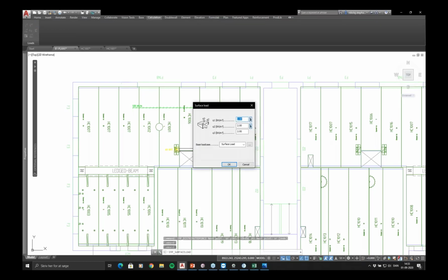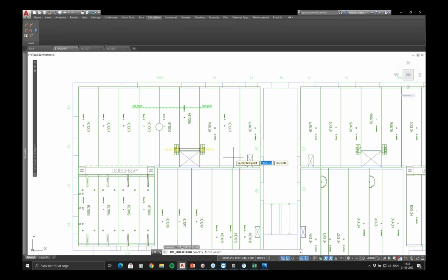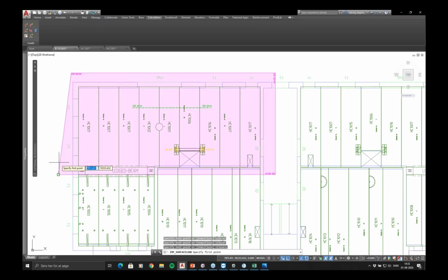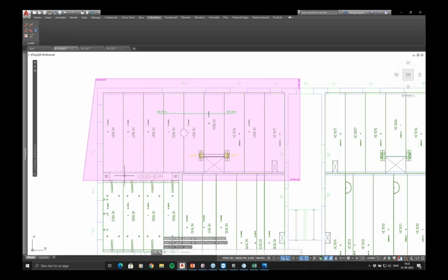And of course I have some surface load as well. And the surface load, if it's the whole surface, I can actually just do like this. I don't even have to think of it hitting the right place. It depends on what I'm calculating, of course, but here I can do whatever I want with that load. So right now I've split it into 3 instead, into point loads, into line loads, into surface loads, which is already much more advanced than what I could do with the other one.